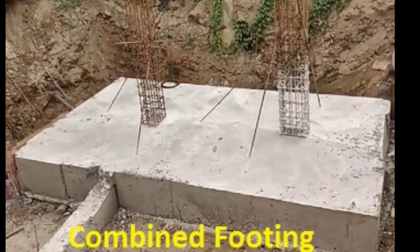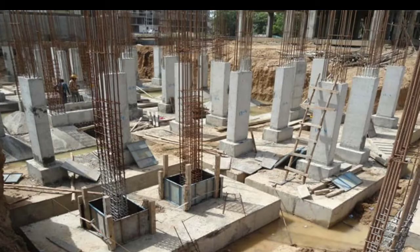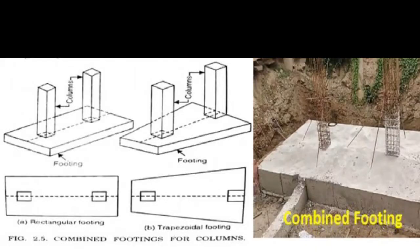This is the combined footing. First point, when more than one column shares the same footing, this is called combined footing. Next point, when the spacing of the columns is too restricted, then if isolated footings were used, they would overlap one another. Next point, when the load among the columns is equal, the combined footing may be rectangular. Next point, when the load among the columns is unequal, the combined footing should be trapezoidal. This is the point of the combined footing.